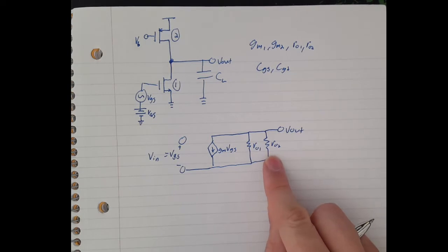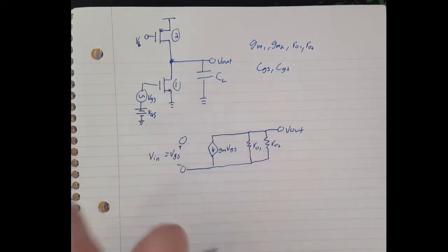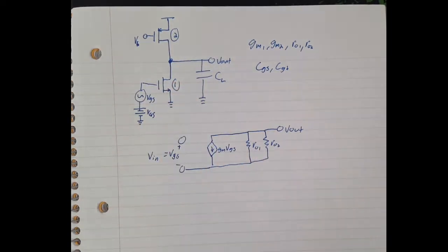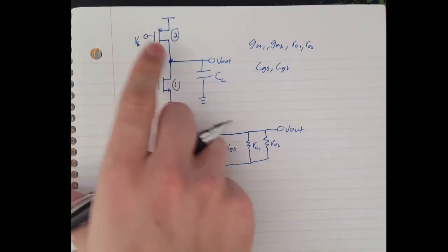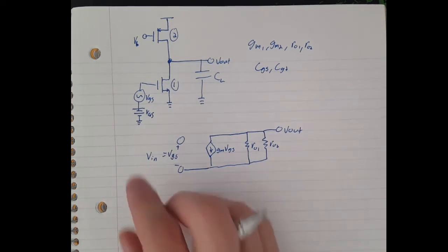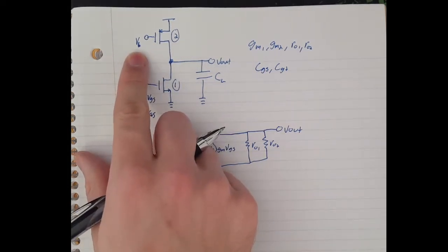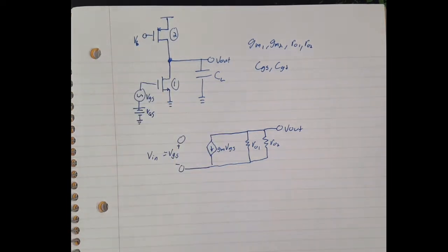And we can change R02 based on what this V bias is. Also, you could have this just being a current mirror, and you'd end up with a similar setup. There would just be a certain voltage here, and it'd be biasing this to get this into a resistor. So if, like in the lab, you need to do something like this and you don't want to have voltage sources, you just wire up a current mirror to this and it would bias this on.